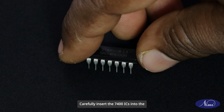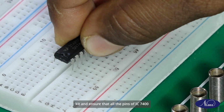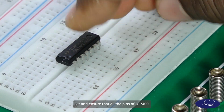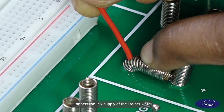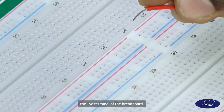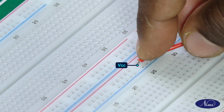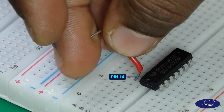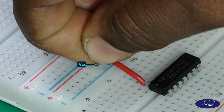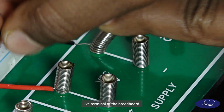Carefully insert the 7400 IC into the breadboard located in the digital IC trainer kit and ensure that all the pins are aligned properly. Connect the +5 volt supply of the trainer kit to the positive terminal of the breadboard. Connect the 14th pin of the IC to the power supply. Connect the ground of the trainer kit to the negative terminal of the breadboard.